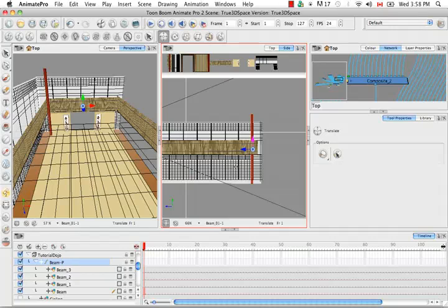And if you remember from our dojo reference, there's actually a beam here, here, here, here, horizontally across, and actually there's quite a bit of woodwork within the shoji as well. So I use the same beam for all of those instances. So what I can do now that I have a beam already made is I can actually duplicate this entire group.